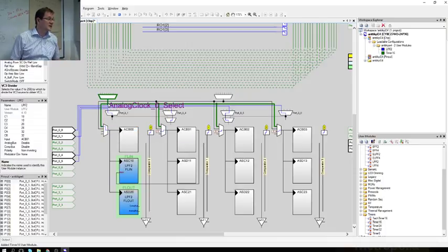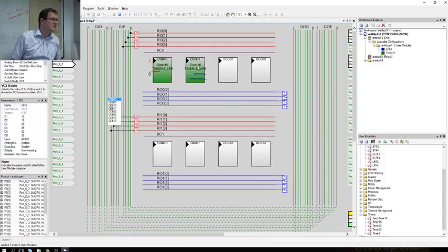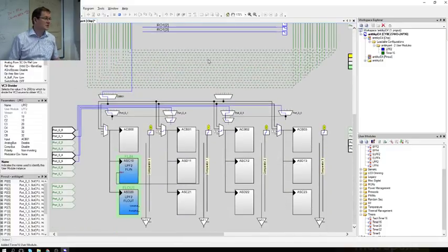Now it's on this multiplexer, which I can connect to DBB01. Now we have a connection from this timer down to this column clock select, and down to this as the low pass filter sampling clock.